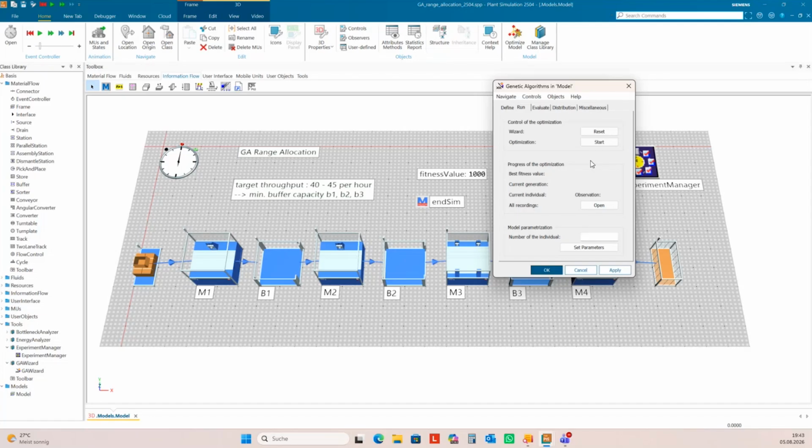Does the GA wizard support true Pareto multi-objective optimization, or do I combine objectives with weights? Yes, you can do this, but you can also create a method to calculate your fitness value. At the end, you need one fitness value. How you calculate this, you need to decide. The most flexible way is to use a method to calculate the fitness value.